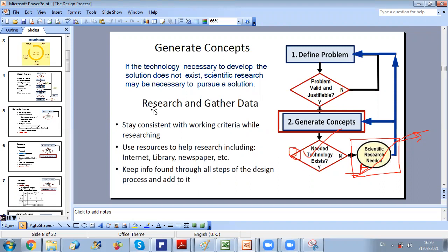So in this case, in mixed ventilation, the concept is to take a portion of natural or fresh air, plus a proportion of recirculated air, and this is to reduce the energy consumption. You will cool it to a certain temperature, then reintroduce it into the space. And of course, you will use a mechanical system. In general, this is the conventional mechanical system, the HVAC systems you use. All conventional HVAC systems are based on mixed ventilation. Is it clear?